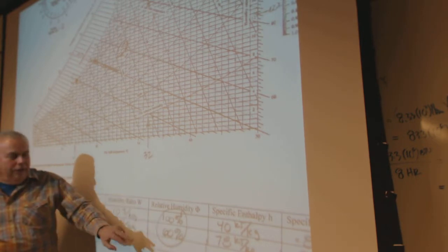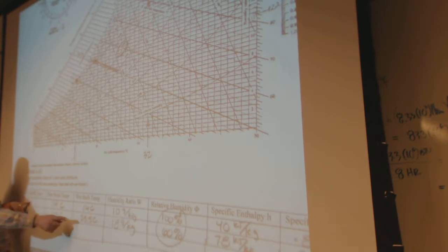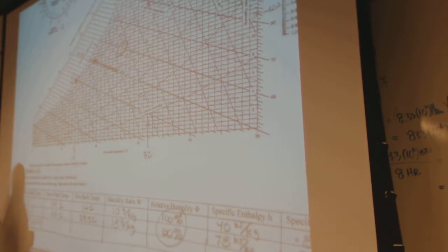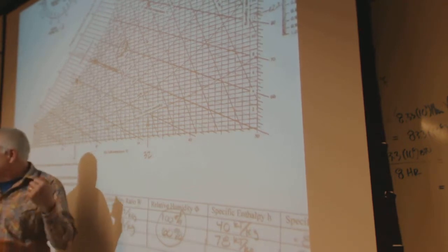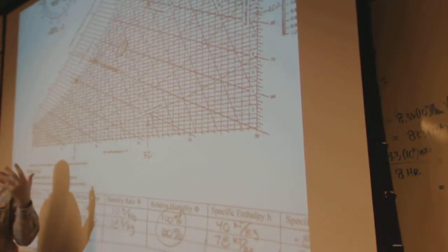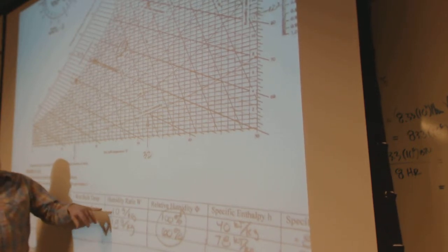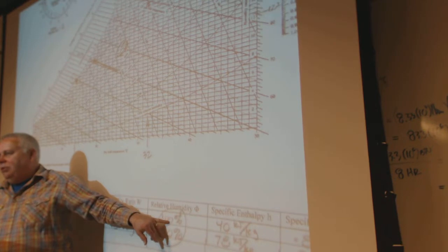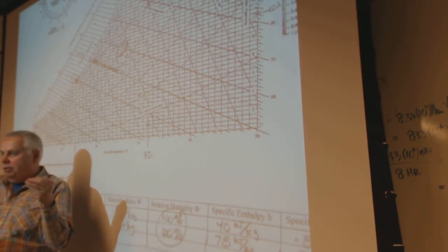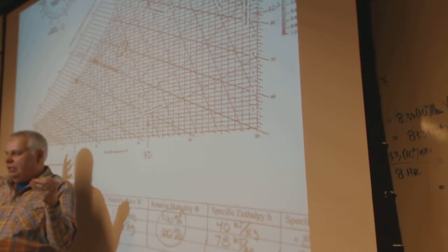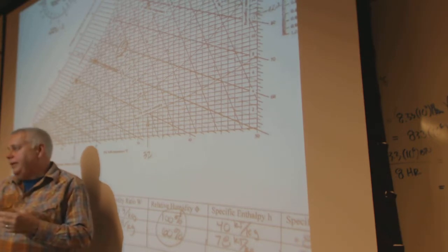And how do they find the relative humidity? They find it from dry bulb and wet bulb temperatures. That's how you get those two temperatures, and that's really how they measure it. And then they'll say it's a relative humidity. Usually what they'll give, like in the back of the room, it doesn't say here's the wet bulb and the dry bulb. It says here's the dry bulb and here's relative humidity. They didn't actually measure the humidity, I don't think. Probably. Well, maybe they did.